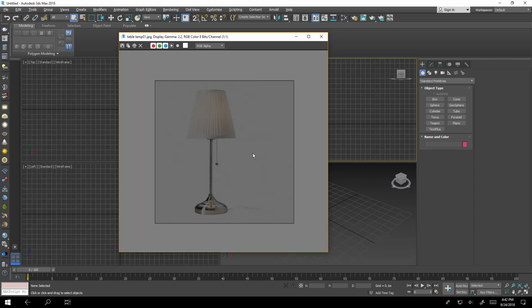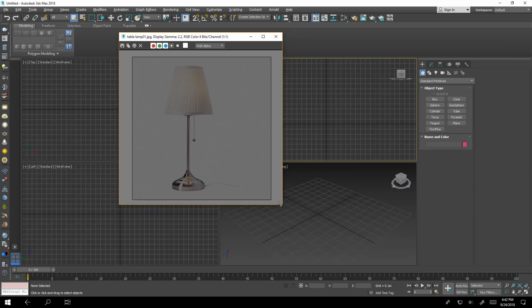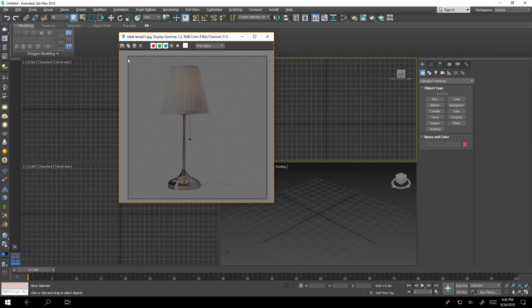If you are gonna use any image as a reference, try to avoid black or white colors. So just reduce contrast in order not to find visual difficulties while working inside 3ds Max. To load this inside 3ds Max, you need to apply it on a plane primitive. This plane has to have the same ratio as your image.